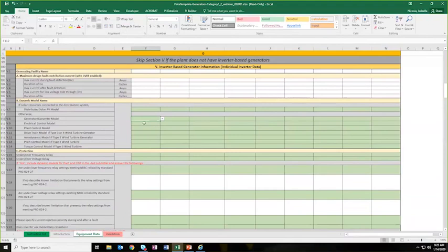And then on the dynamic model, for solar resources, if it's a PV and DG distribution generator, then use either the PVP1 or DERA model. Otherwise, for transmission connected, here are the models you need to include. First is the generator model, right now only REGC_A is available. And then the electrical control model, which will be either A or C.